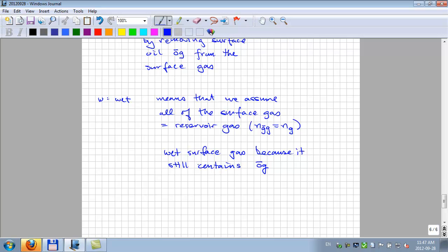But if you use that equation, you're saying that I get no condensate liquid, I only get surface gas. So it's a very pessimistic way to do your engineering. It's a way to get you a job demotion instead of a job promotion. And the first field in Norway, Ekofisk, that was developed because their reservoir simulation models made this assumption that gas did not yield condensate.